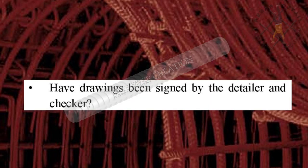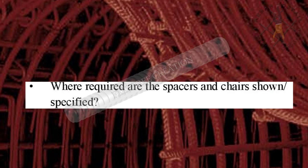Point 26, are schedules correct? Point 27, have drawings been signed by the detailer and checker? Point 28, where required are the spacers and chairs shown or specified?